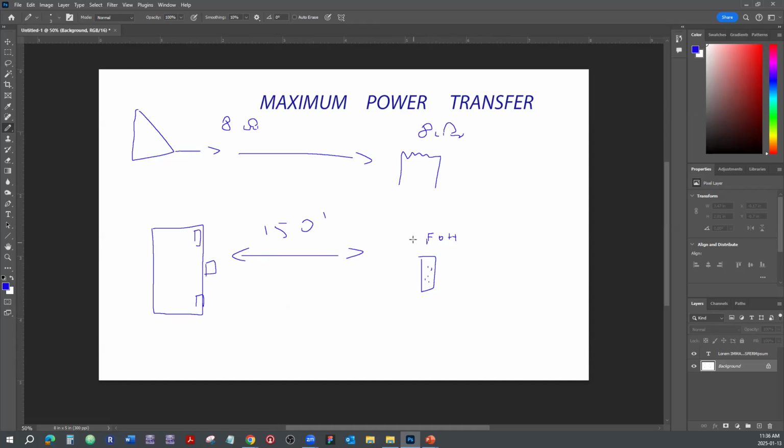You don't want the amplifier to be here. You want the amplifier to be somewhere close to the speakers, because with 8 ohms, or when it comes to staging like that, you're going to have maybe even 4 ohms, or maybe 2 ohms as far as speakers. Then the resistance of the wire would be comparable to the impedance of the speakers, and some of that power is going to be just lost in the cable. So you want the cable between the output of the amplifier and the speaker to be the shortest distance that you can have.